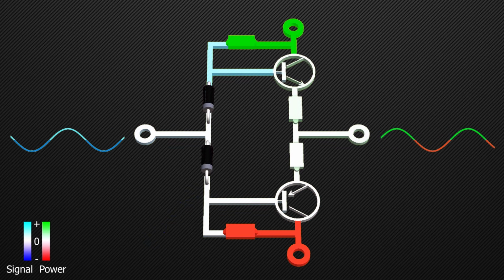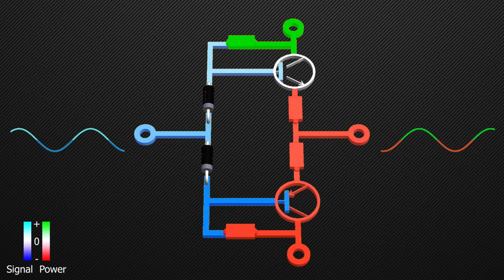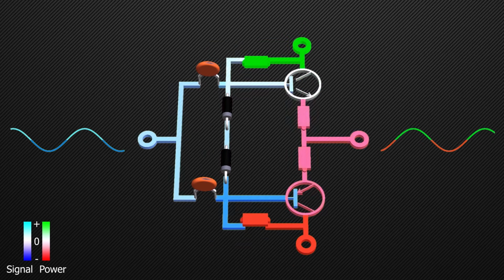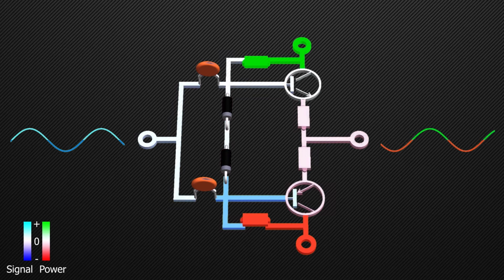Now, any changes at the input will cause the voltage at the other ends of the diodes to change with the bias of 0.7 volts. This is how we bias both the transistors. You can also connect the input signal at other terminals of the diode. We also add capacitors to filter any DC from any direction, and to avoid short-circuiting the diodes. This is how amplifiers of Class B and AB work.